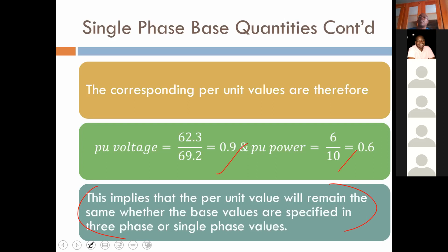All right, now, I just mentioned the fact that we had a base value of 30 MVA, but I also spoke of 18 megawatts as being the actual, yes? So I'm going to now speak to some conventions that must be applied in doing per unit. We have already established that the S base, you select that arbitrarily. We know that we select the kilovolts depending on where we are in the network.